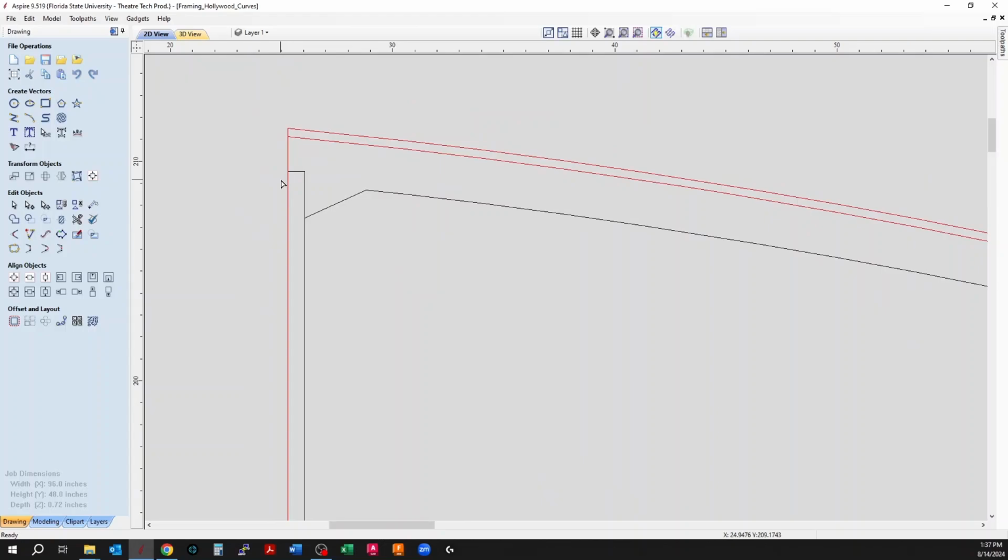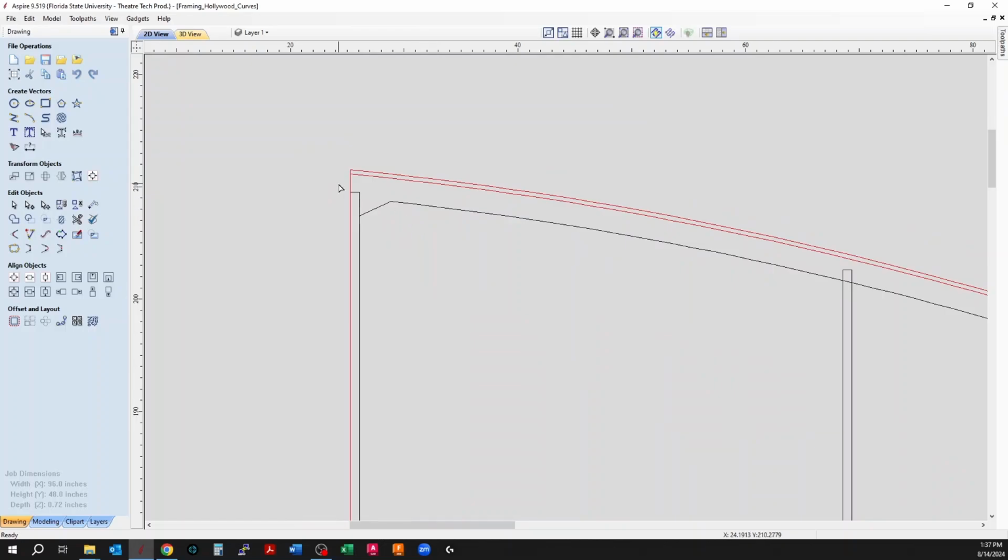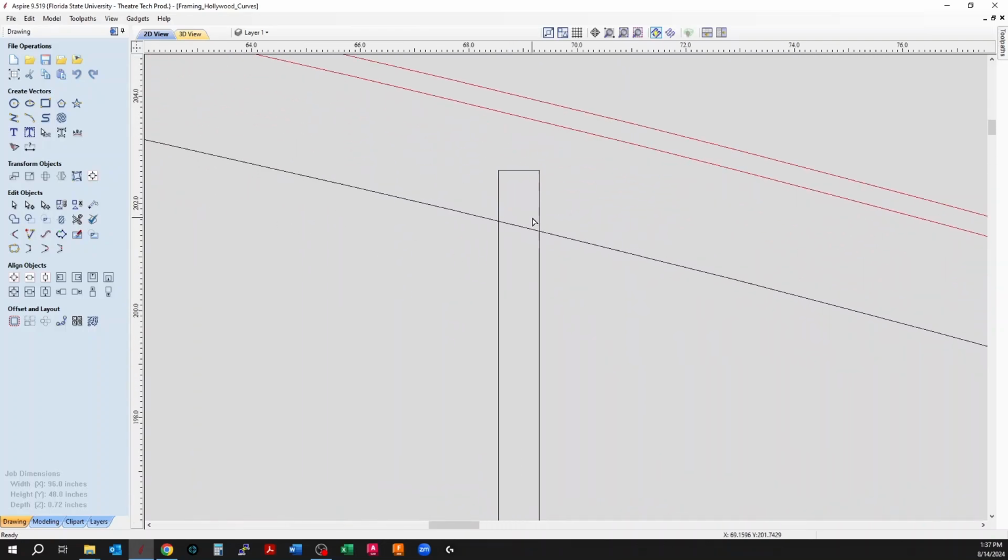So if you see here, now I can shoot in with narrow crown staples into this front piece and the back piece, because again, we're doing a Hollywood style framing construction, right? So that is going to make that piece fit well. And then same thing over here, and maybe this is farther in than I need to be. It probably is, so I can adjust that. And then again, go into node edit mode by hitting N, select the line that you want to modify, and then just start to modify, right?